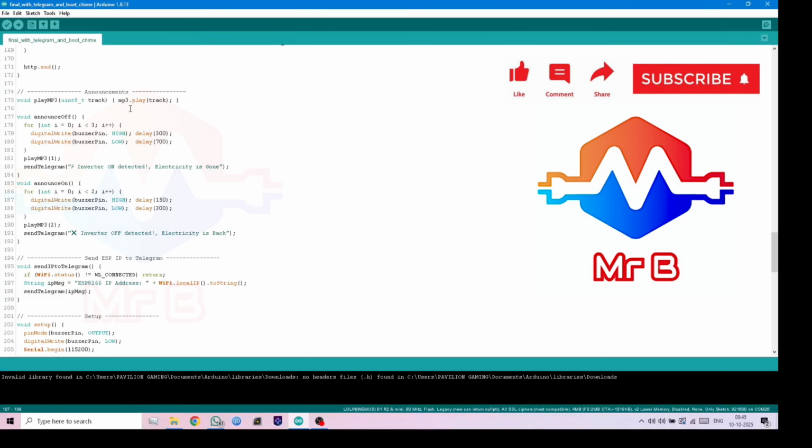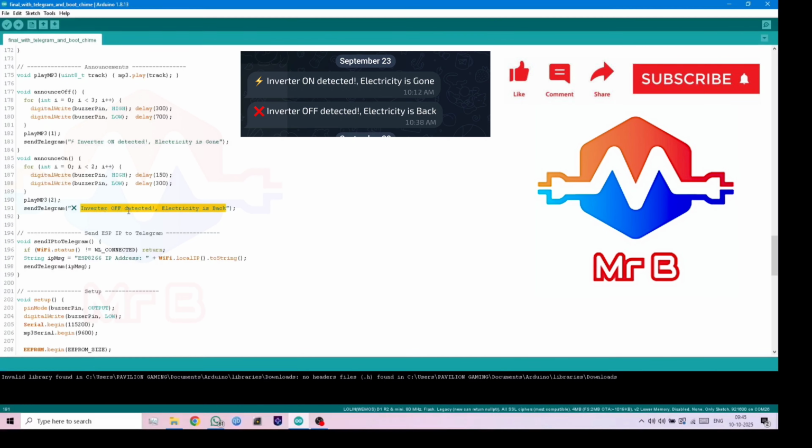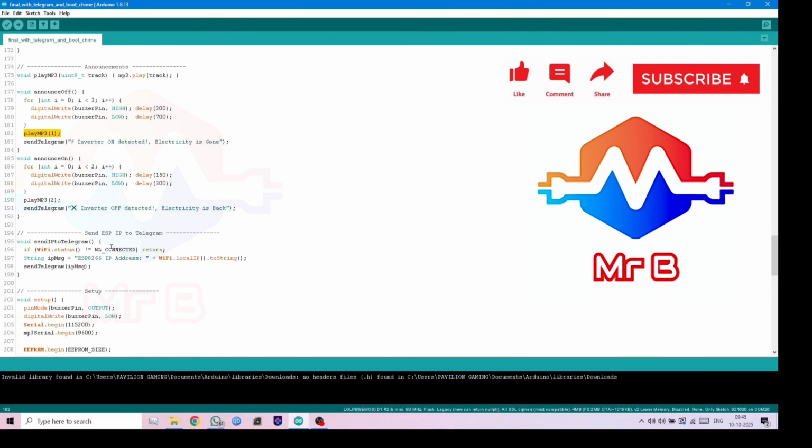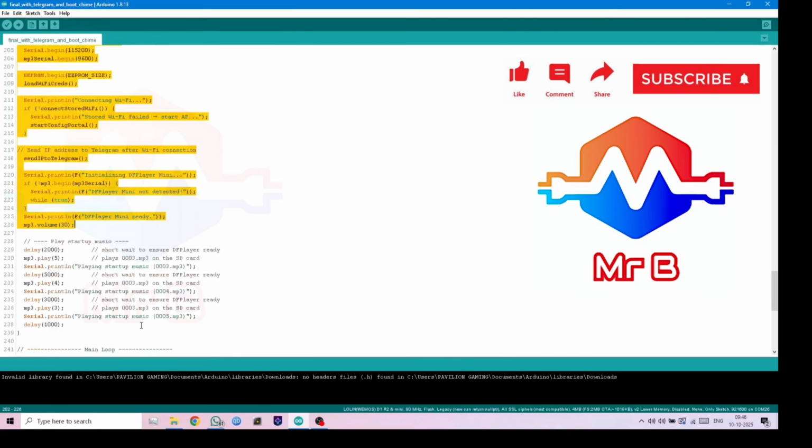So here you can see that I have got all the different tracks over here. This is play MP3 1, this is the first track. This is the play MP3 2, second track. So just like that, all the different tracks are laid in over here. For example, play MP3 1 signifies that inverter on detected electricity is gone, and this is the part where you can change whatever message you want to display on the Telegram chat section. This is the line, and this is the other line where you can change to give any custom message over there. And these are the two lines where the two MP3s that I have linked get linked to this programming itself. Then we have got the void setup part, this whole thing.